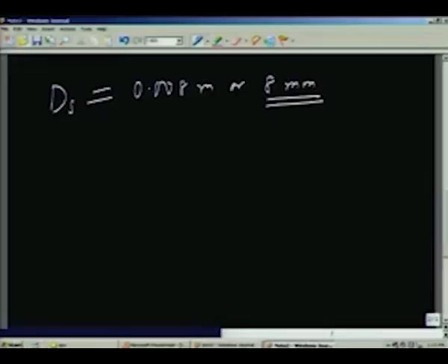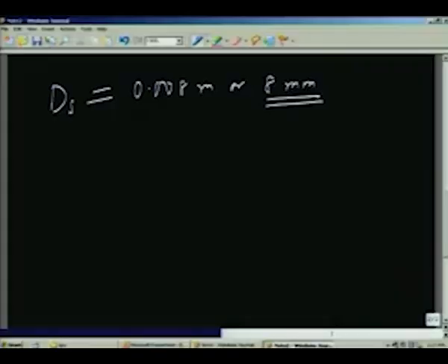So, the diameter of the tube must be at least 8 millimeters or even more, because at 2 meter per second, that velocity is constant, 100 milliliter per second will flow through that, but there is a lower limit. So, it could be more, that means I have to choose a diameter of 8 millimeters or more. If you want to work at the limit, we can just take a value of 8 millimeters for that. So, we have some idea now about the isokinetic sampling.